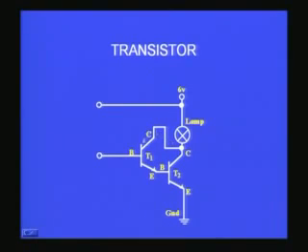So you have now formed a new transistor with 1 base, 1 collector, and 1 emitter, but internally you have 2 transistors combined as shown in the figure. When this happens, this is called the Darlington configuration. What is the advantage of this Darlington configuration? A very small base current will provide a large emitter current in the common emitter configuration.